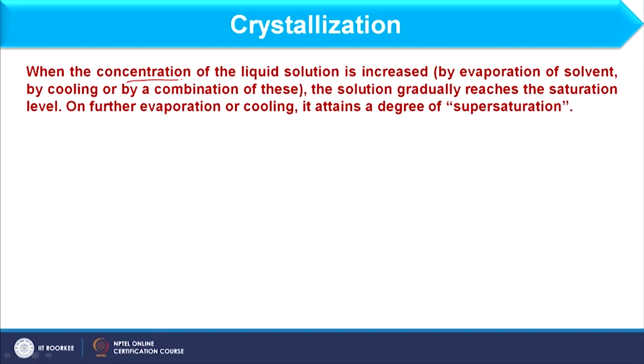When the concentration of the liquid solution is increased, and how can we increase the concentration of the solution, either by evaporation of the solvent or by cooling or a combination of these two, the solution gradually reaches the saturation level. When we further evaporate it or cool it, it attains a degree of supersaturation. That is a very important word when we are considering crystallization: the solution should be in a supersaturated condition.